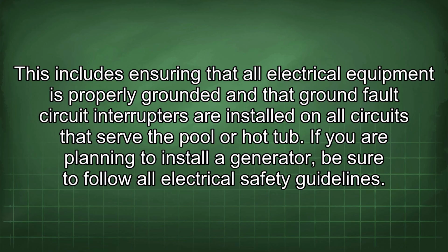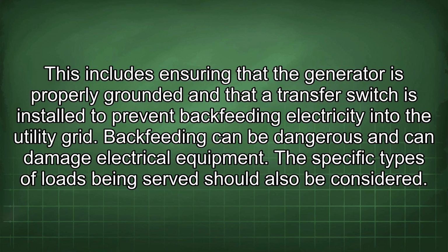If you are planning to install a generator, be sure to follow all electrical safety guidelines. This includes ensuring that the generator is properly grounded and that a transfer switch is installed to prevent backfeeding electricity into the utility grid. Backfeeding can be dangerous and can damage electrical equipment.